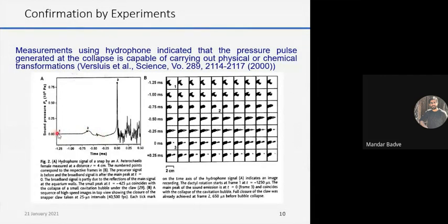This is the normal pressure condition. Then when it closes and forms that velocity jet, the pressure goes down, and during the collapse, the pressure suddenly increases, right? So you can see the sudden increase in pressure. This sudden increase is because of the collapse of the cavity, right? And then it comes down and slowly recovers as it travels further.